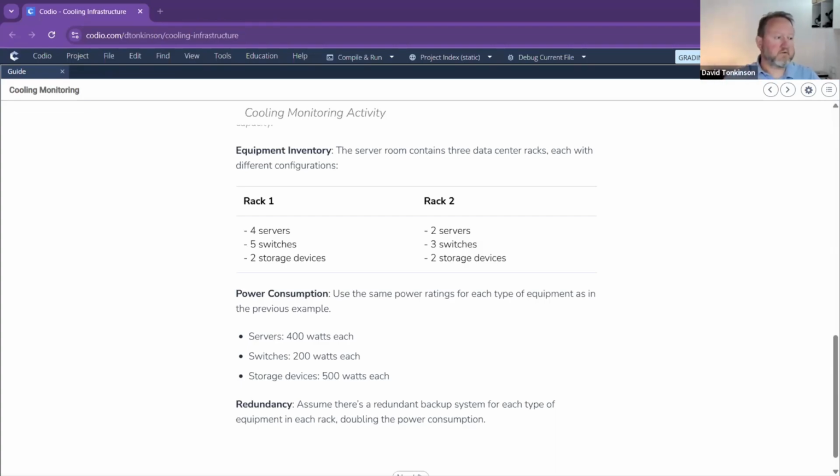And we've got 20 of these systems, basically replicated across our site. So we can calculate the BTUs, and it's important you look at your BTUs in terms of balancing that. I wouldn't want to put all the hot stuff into one rack and simply blow my air conditioning through the entire building. So if we balance the BTUs across the different cold aisles that we've got, we then know we're blowing a balanced amount of cold air into each of those cold aisles.